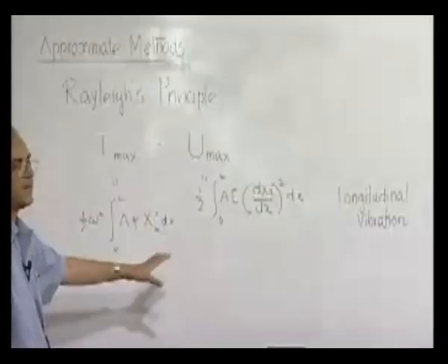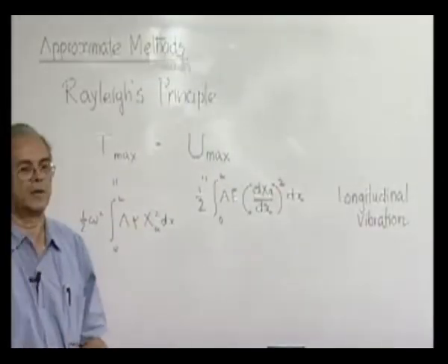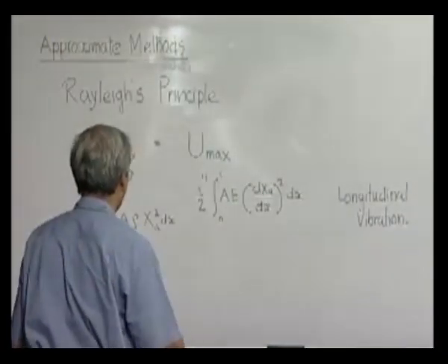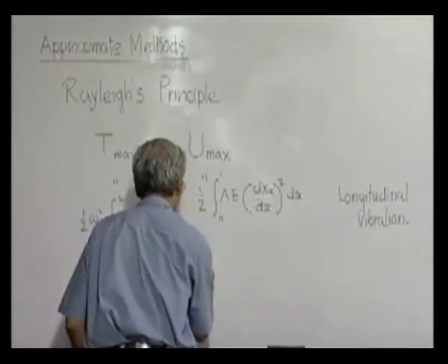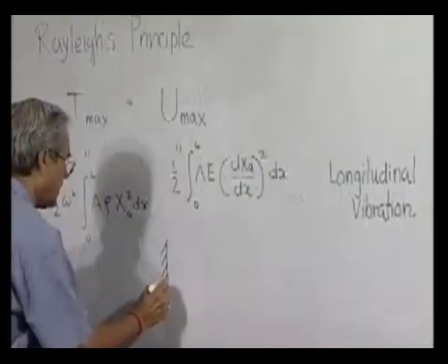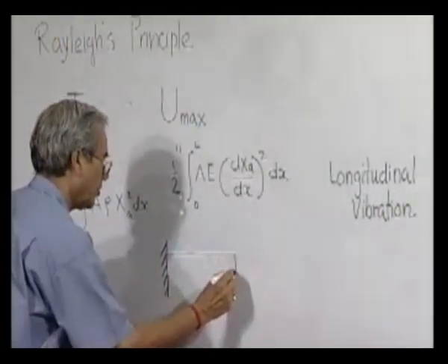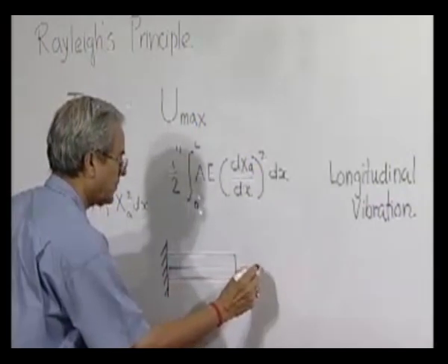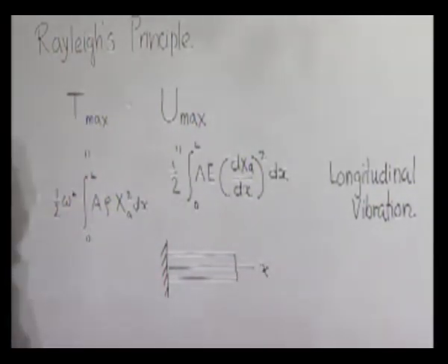And we have seen by applying this method to longitudinal vibration of a cantilever bar or one end fixed bar, that our result was reasonably accurate, even though we assumed the mode shape which was not satisfying all the conditions.